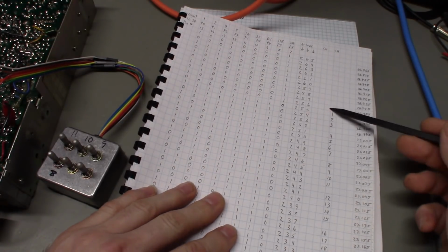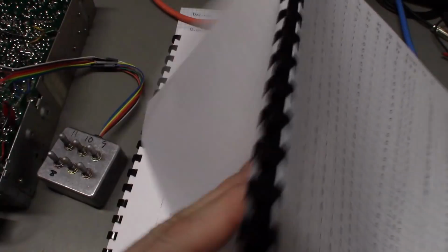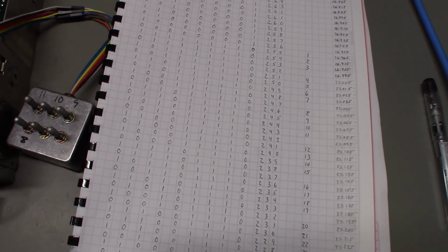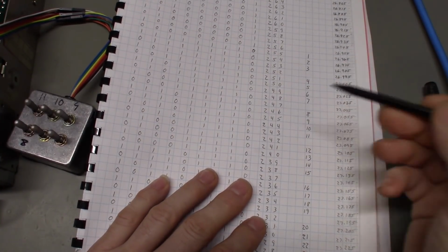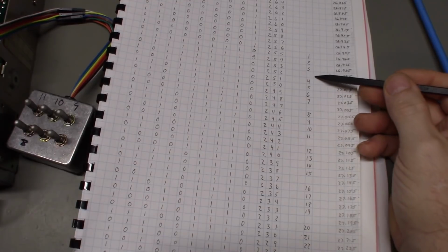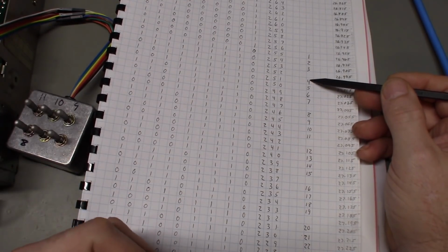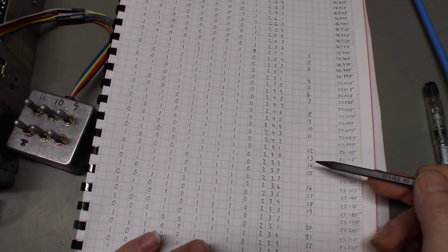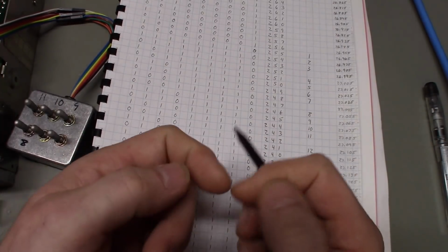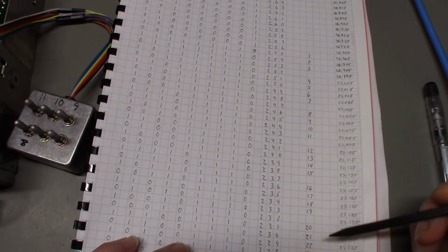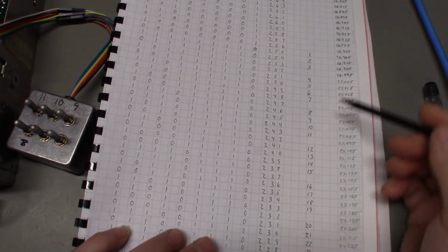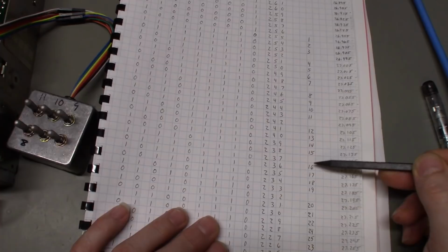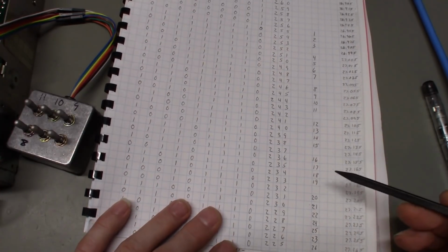So if we continue on here, you can see I got from like 1 to 26. Oh, one other thing, in case you're not familiar, most people are that do CB, but if you're not, in the CB band there are skip channels. Way back in the past, I think they were used for business band originally. They're commonly referred to nowadays as the A channels, and if I'm not mistaken, most of those channels are now mainly used for remote controls, like cheap radio controlled cars and stuff like that. I think that's where most of the missing CB frequencies are actually allocated. But as you can see, there are channels missing between 3 and 4, 7, 8, 11, 12, 15, 16, 19, and 20. So there's 5 missing channels.